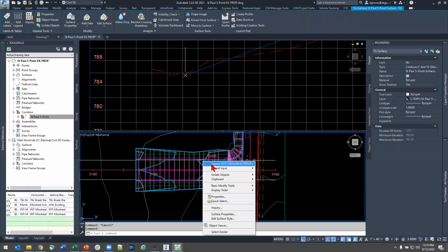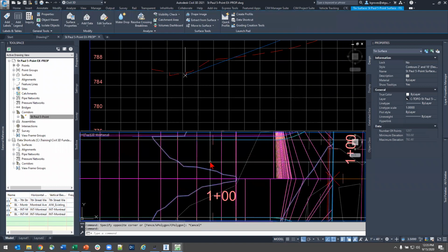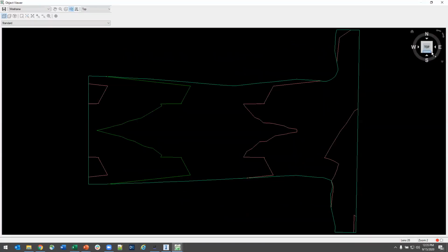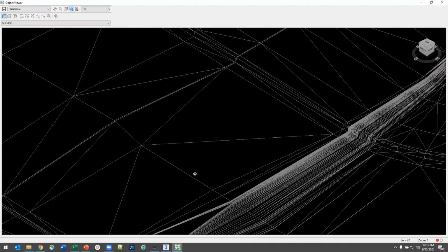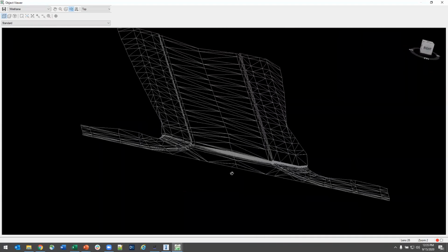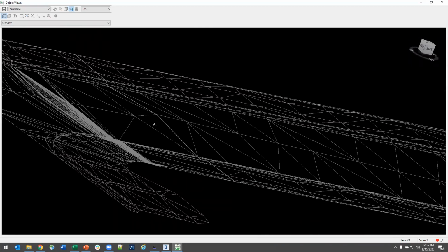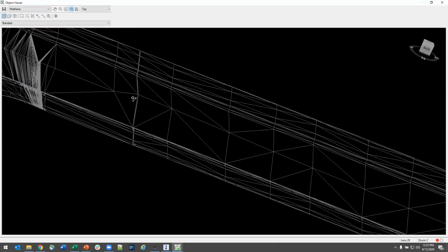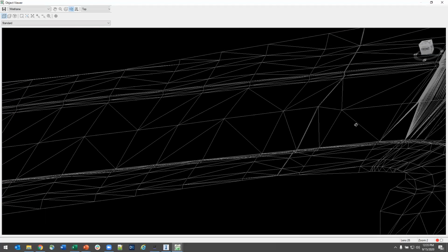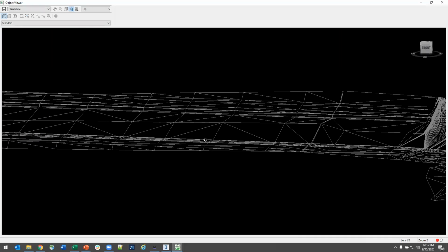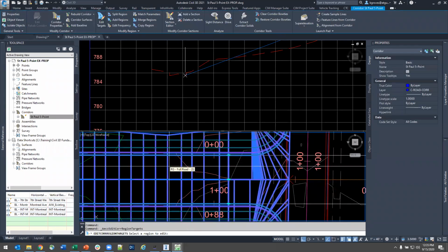using top links and a shrink wrap outer boundary, because this surface is going to give me a really good indication as to whether or not I got all of my targeting right. So if I bring this into Object Viewer, or if I'm even just looking at the contours and I notice a lot of jags, it's going to be pretty obvious where I'm having issues. So it looks like, for some reason, over here, I've got a bit of a bump, and that could be related to my region transition. So I'm wondering if I got any of my targeting wrong. Let's go back and review.